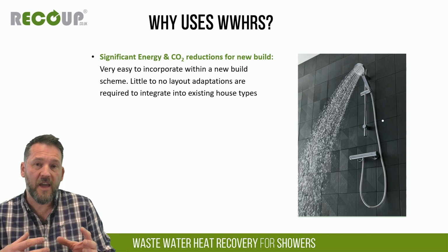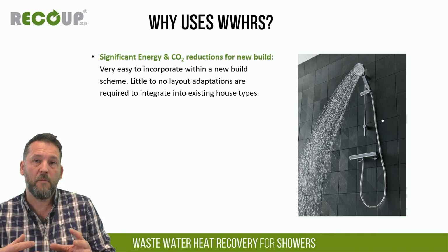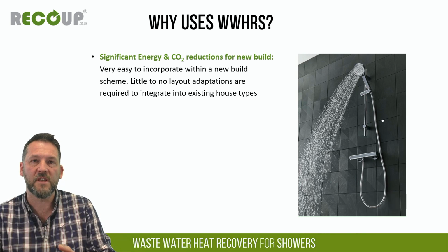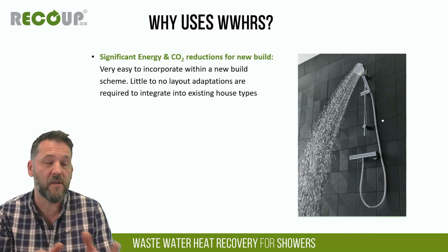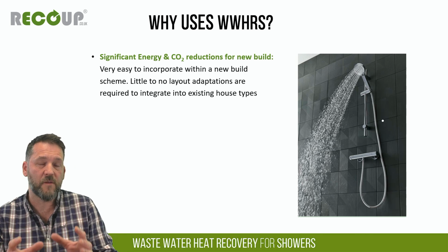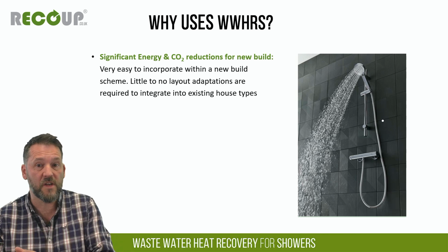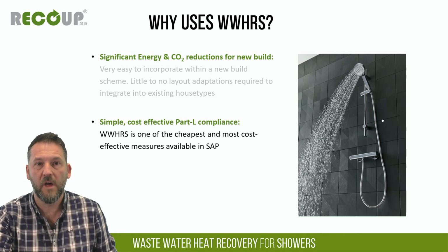It's a heat exchanger technology which takes the warm waste or the heat energy from the outgoing shower waste and imparts that into the incoming cold water main. And we'll look at that in a bit more detail in a moment. But essentially it's very easy to incorporate into new builds. It doesn't require a great deal of design knowledge or change to existing house types, which is why it's very much a technology that's been focused on for the transition into new build regulations.